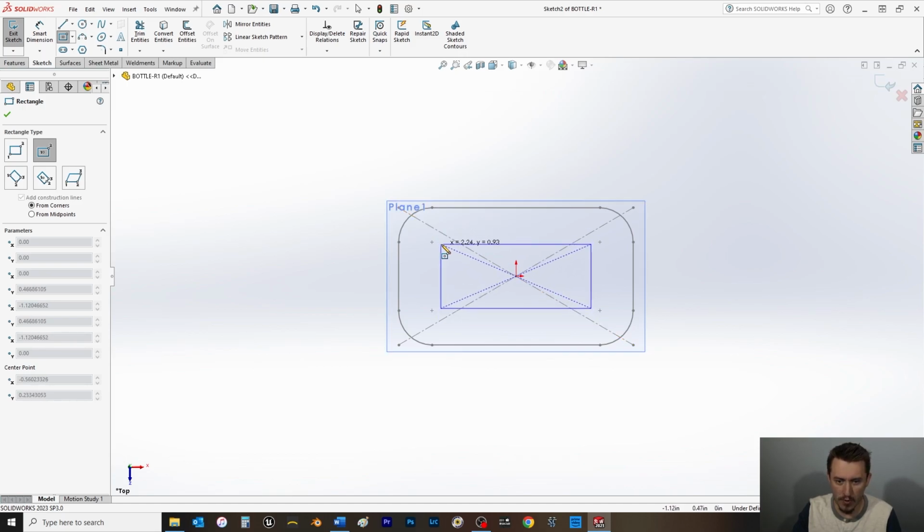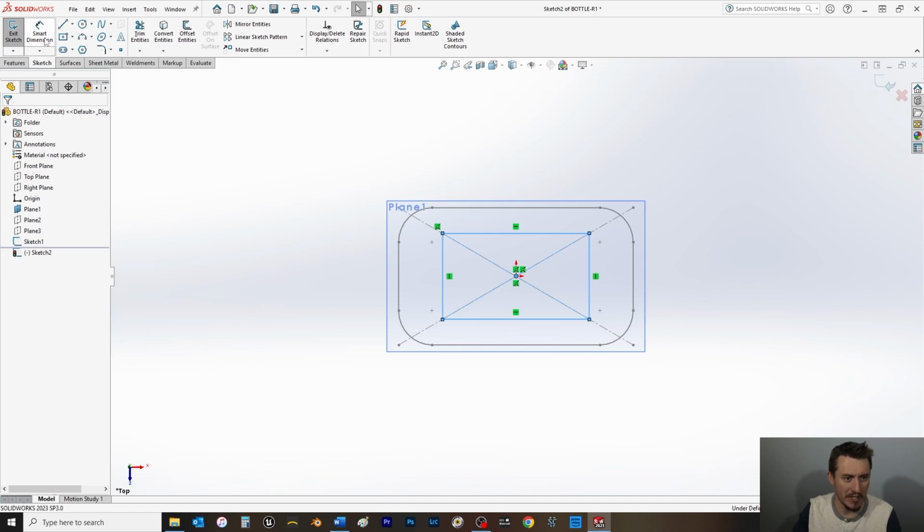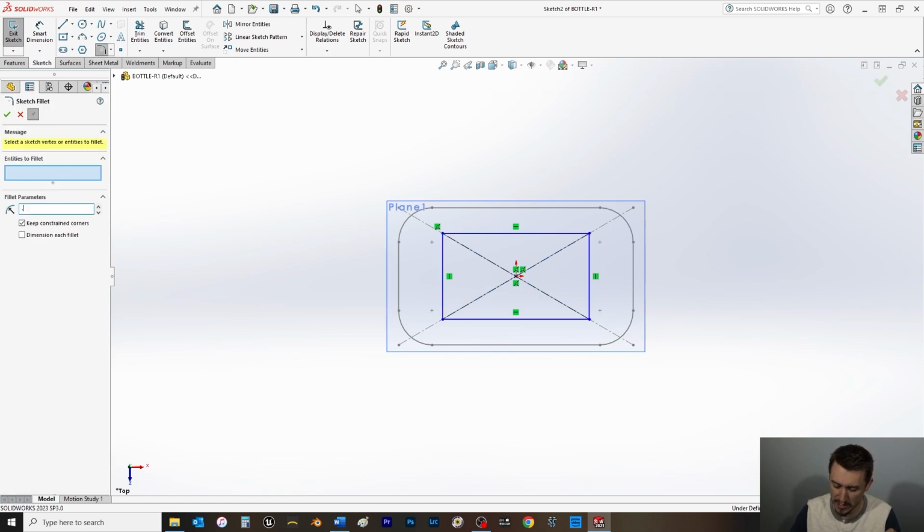And this corner that my number 2 pencil is connected to, make sure it is coincident with this diagonal reference line here, like such. Now, things are a little different here. First, the fillet is still the same, so the sketch fillet should be 0.5 inches, and our selection is all 4 corners again.